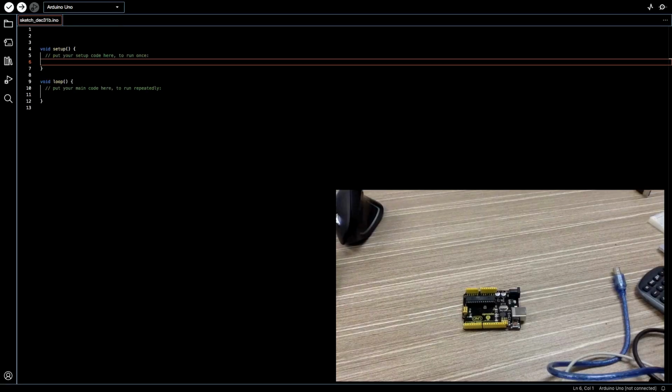First, you need to download the Arduino IDE software from the Arduino website. Once you have it and you open it, this is essentially how your sketch will look. It's empty. So your void setup is what happens once in your program. It only runs when the program is started, once, and then it jumps to the void loop, and then it keeps looping again. So it runs continuously.